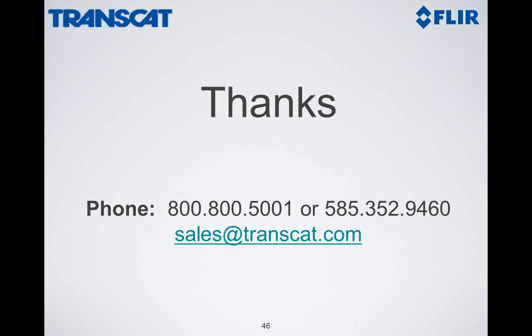Should I change to get better IR pictures, or should I use the 30-millimeter IR lens? If they're blurry, that means you're not in focus. So what I would recommend is finding where the focus is of your camera. Keep pulling, get to as close a focus as you think it is, and then keep pulling back until the camera is in focus. Without knowing the size of your component, it's hard to tell you which lens is appropriate for you. But I would always make certain.